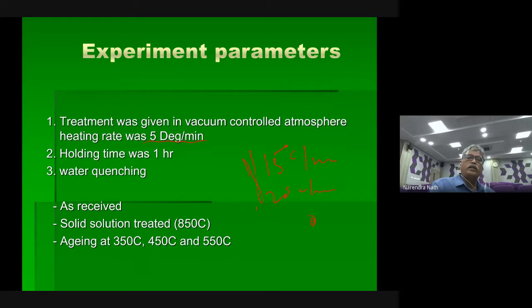Okay, so again, holding time. Holding time depends: 1 hour, 2 hours, 3 hours, depending upon your transformation curve one can choose. And if you want to have that phase, you can think of quenching or else natural cooling. Okay, so to study these things, first we have to think of the as-received condition.